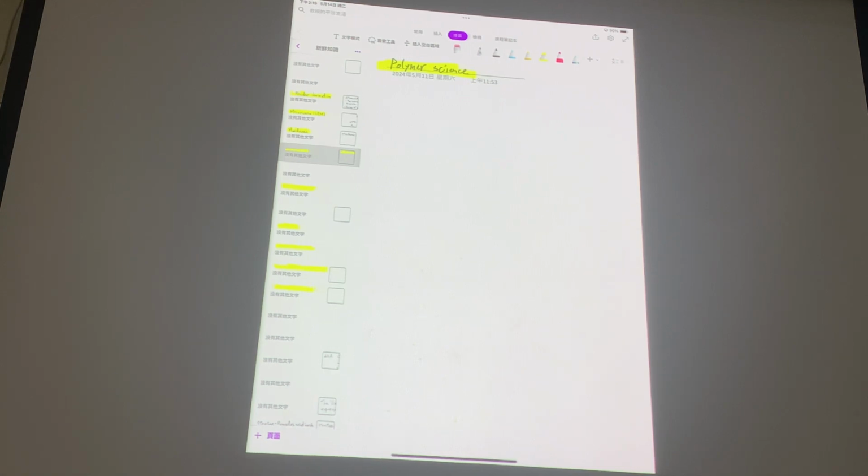Anybody? Renan, do you want to volunteer about the difference between thermoplastic and thermoset? Thermoplastics are softened by heat. You can go into a molten state and then by cooling you can go back to its state. But thermosets, once they are given a shape by application of heat, will take that shape for a longer time. If you heat it again, it will burn. Yeah, I think so. Roughly about 85 to 90% correct.